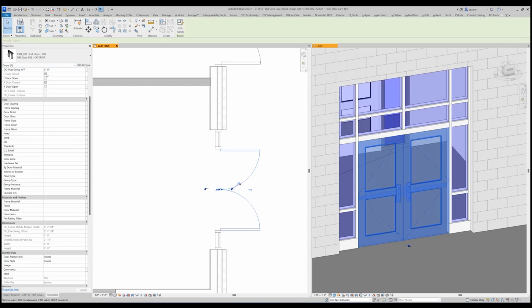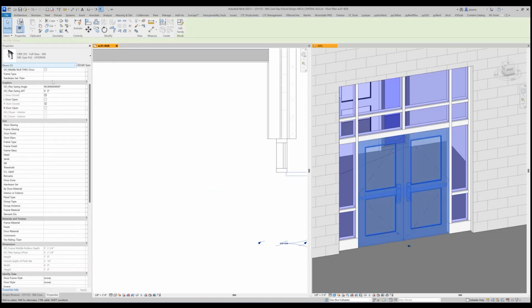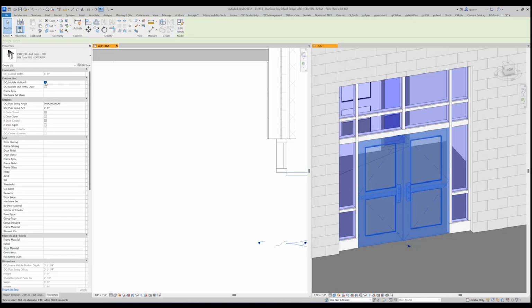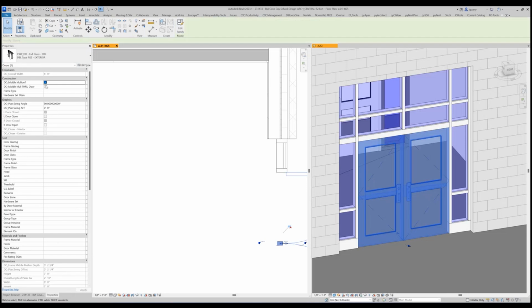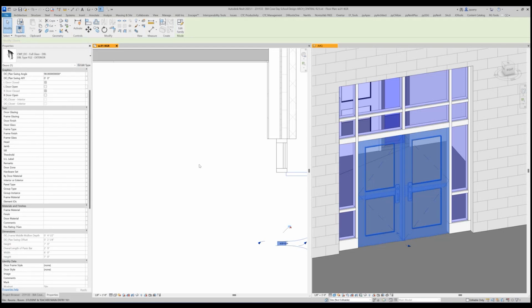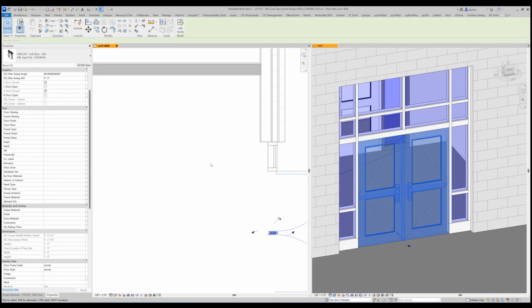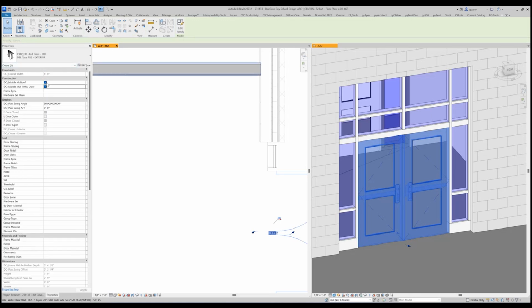And let's say I, just so you can see this, if I pick this middle mullion, watch what it does. See how it grows it behind it. These panels don't change in size. But if I send it through the door, it shrinks those panels, even though they're still 3 foot. You know what I'm saying? Does that make sense? Yep. Awesome. Alright, cool.